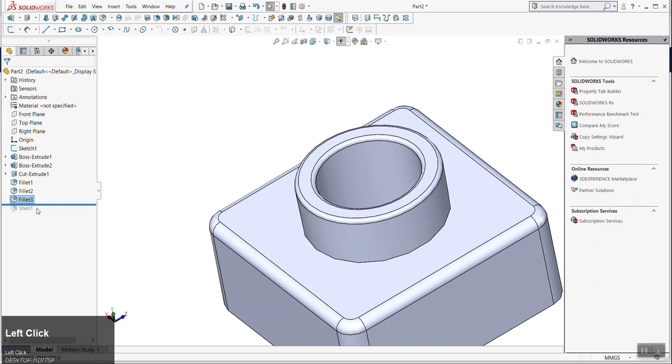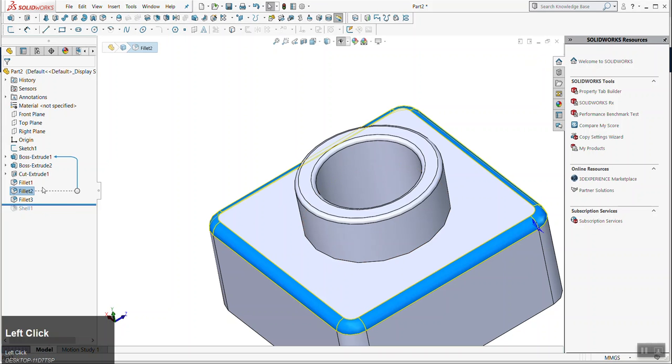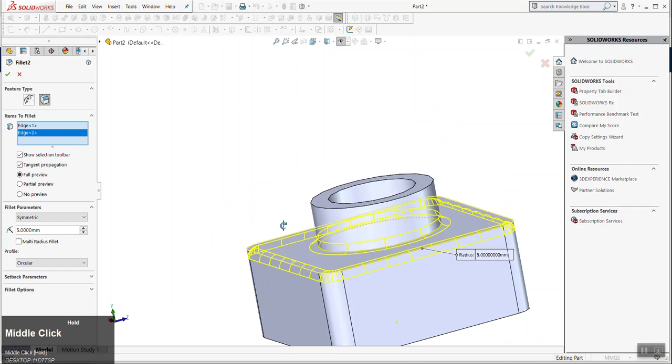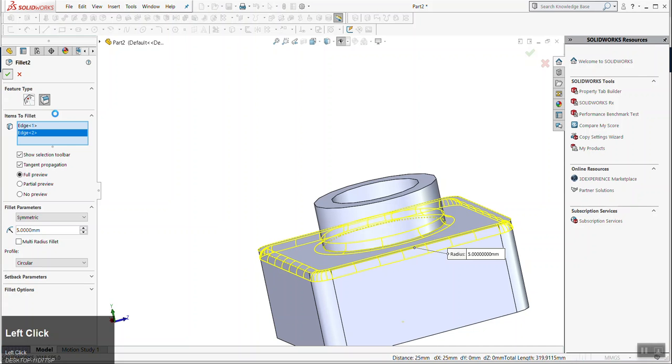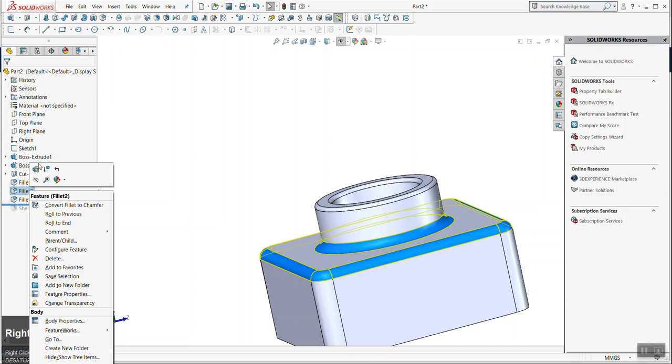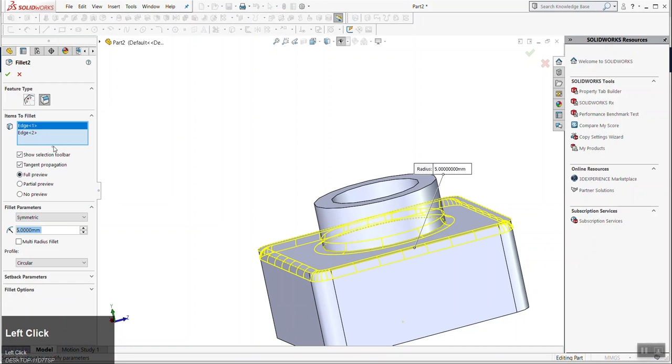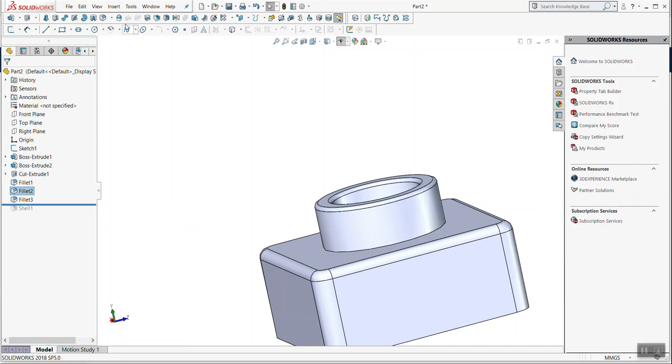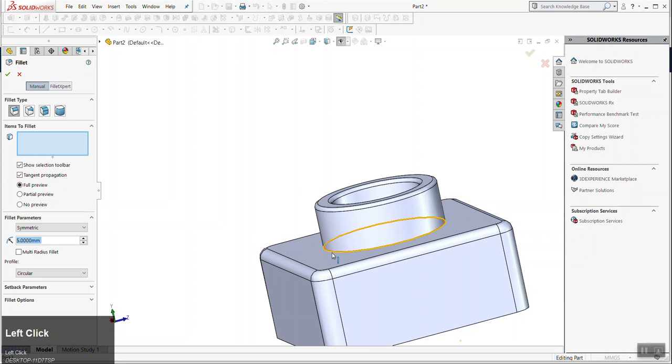Sometimes you can combine edges and fillets. If I know that I want this inner edge to be the same, I can edit this and select another edge. I think the tutorial had you guys back out of it, deselect an edge, and then create a new fillet for the value. Type it in on this drawing what the value is, so I'm going to just make it up. But we'll just say it's 5 also.